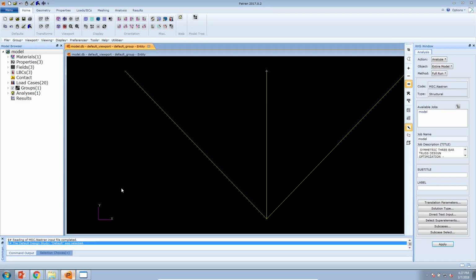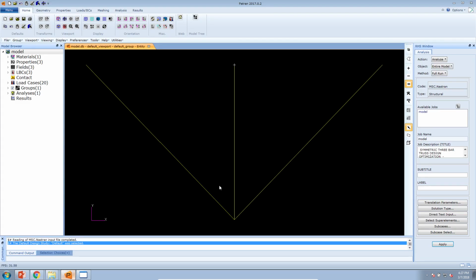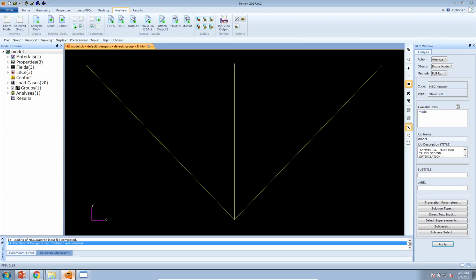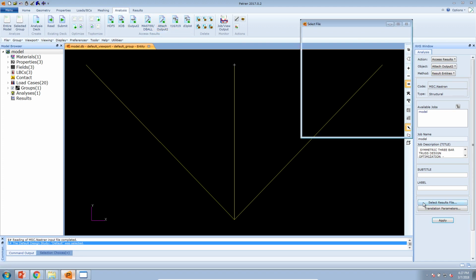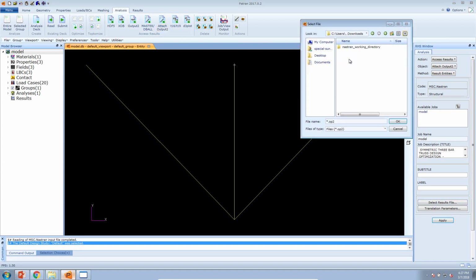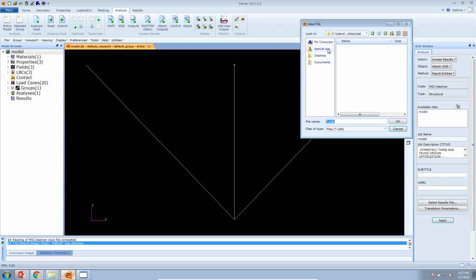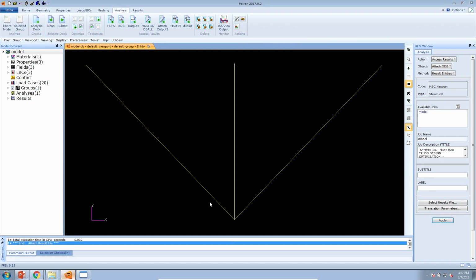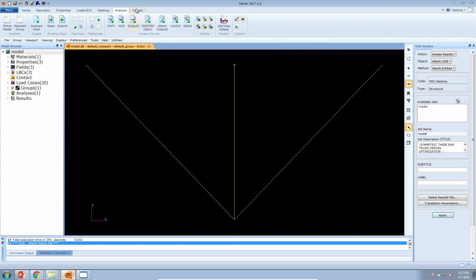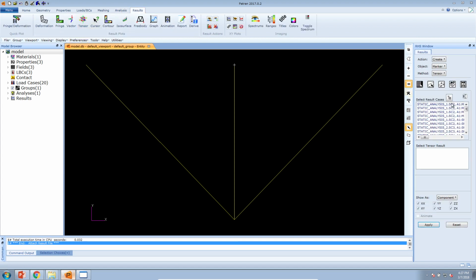So it'd be worth actually showing you that value in Patran. So if I go and I upload the newest result file, this result file, as before, always has both the initial and the optimized parameters. So here, let's go ahead and upload this new XDB file. For you, it might be an OP2 file.